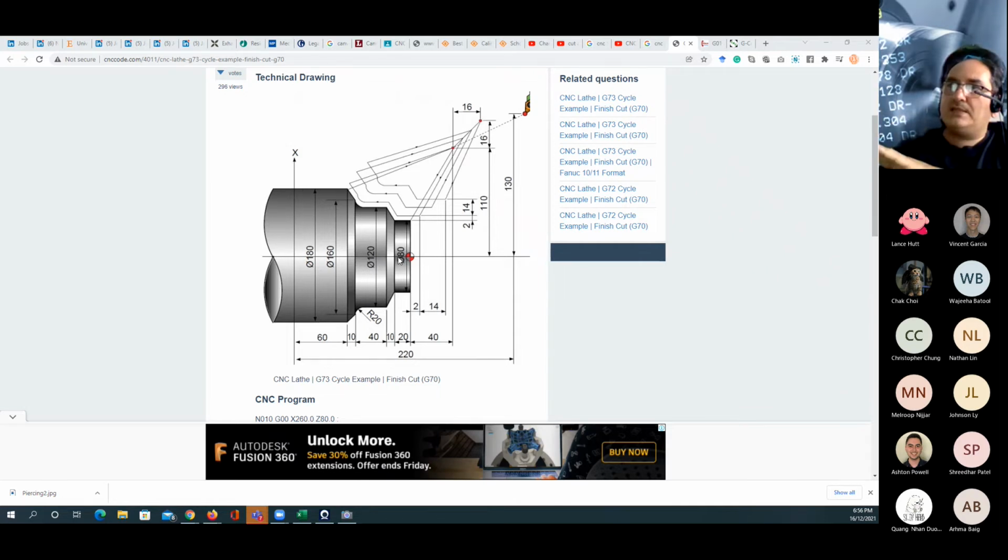Use the depth of the cut here to be something about 2 millimeter for the roughing and 0.25 millimeter for the finishing. Do you think that you can take this challenge? It shouldn't be hard. As I told you, it's just 2 dimensions. It should be all right. Should be all right. Yep.